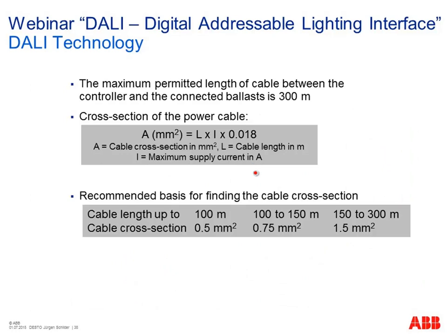So some words here about the cable. According to the worldwide standard, it is possible to use one cable with the supply voltage and the DALI. Here's a recommendation, or maybe a mathematical approach, how you can calculate the cross section of your cable. For example, here we have the cross section in square millimeters. Then we need here the length of our cable of the DALI system. So each meter, the total length of each meter of the cable multiplied by the maximum current.